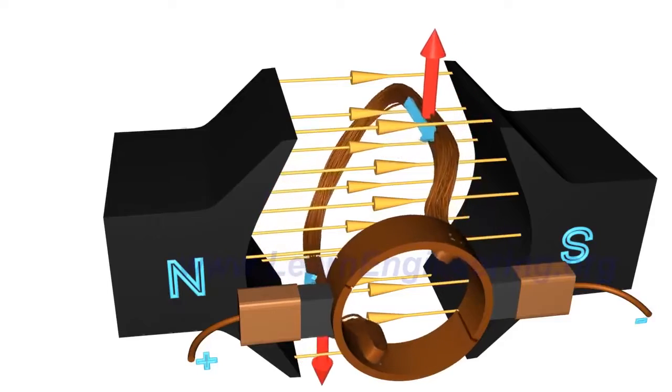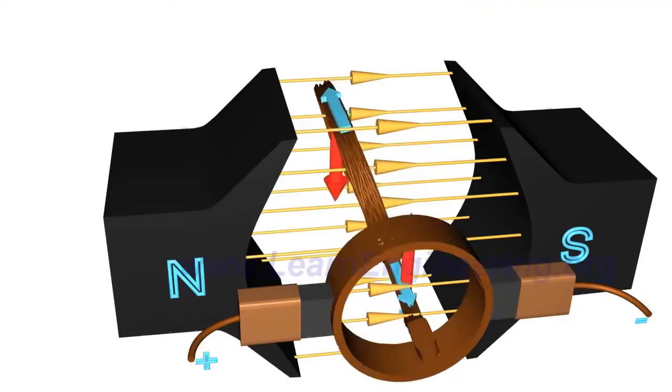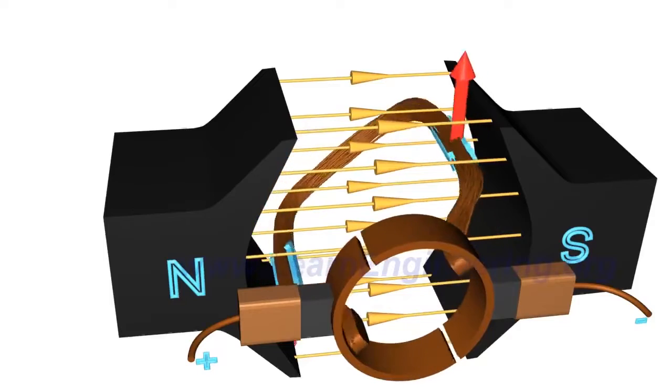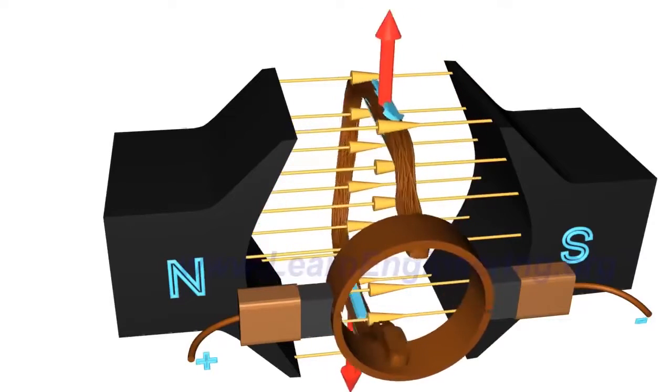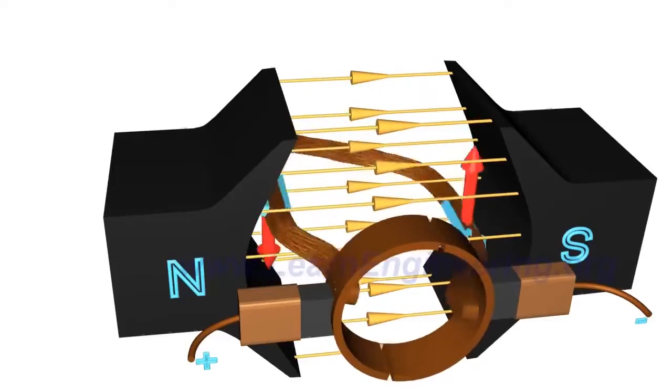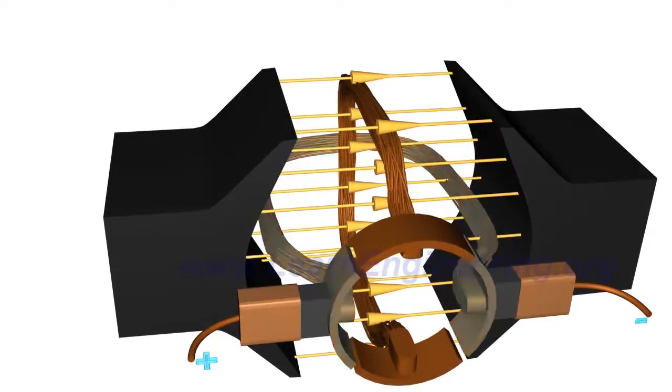When the current carrying armature conductor is in the 180 degree position, the armature is nearly perpendicular to the magnetic flux. There will be an irregular motion of the rotor where the acceleration of the rotor decreases, making the speed inconstant. To overcome the problem, add one more loop to the rotor with a separate commutator pair for it.